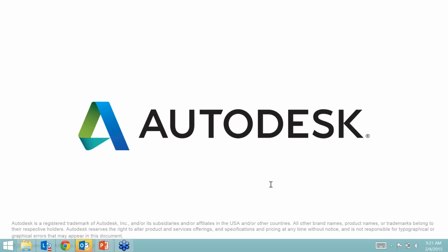Currently, we are working on an integration with ANSYS with Advanced Material Exchange. So instead of only supporting Abaqus, we would also support ANSYS, which would allow us to map data from Moldflow to an ANSYS structural simulation. And we're also working on performing that for unfilled plastics, both in the linear and the nonlinear sense.